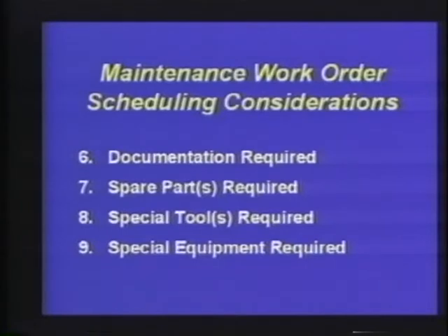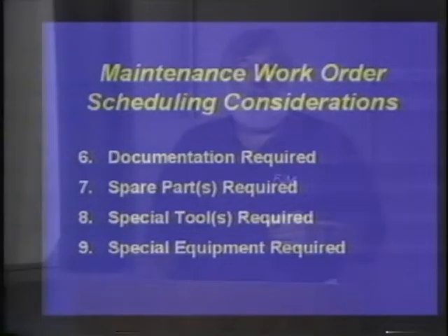And this is required relative to the feedback from the storeroom to the planner scheduler to indicate whether all of these items are ready to be released, or if there is a shortage, then maybe the planned maintenance work order would have to be rescheduled within the plan prior to actually developing a schedule release date.